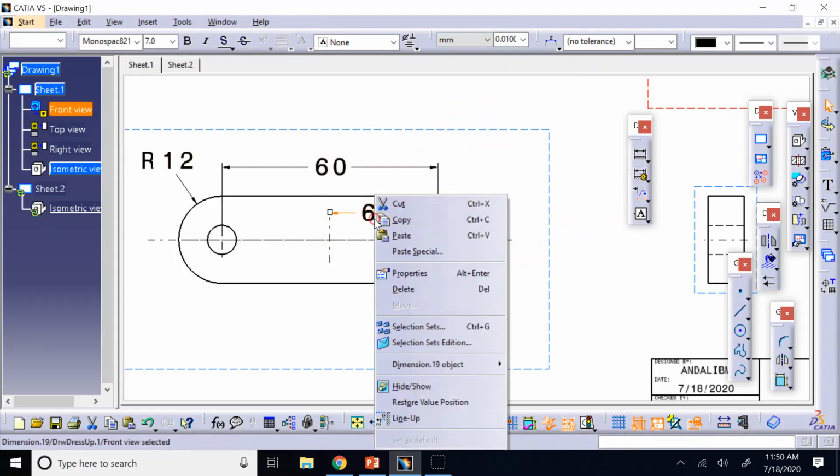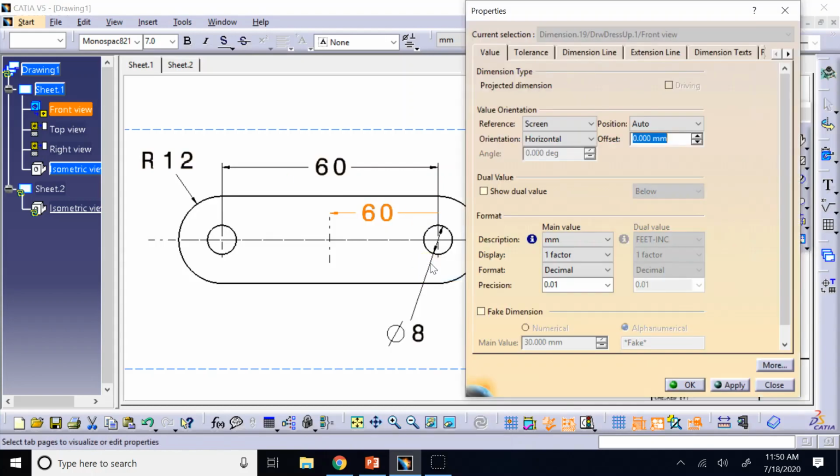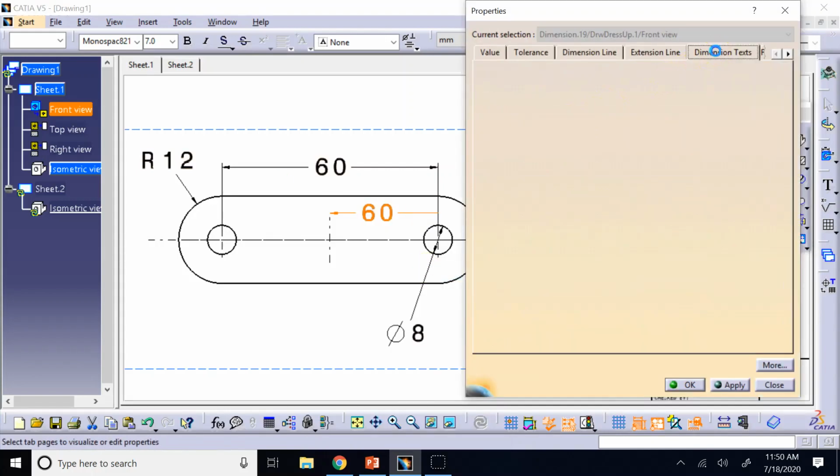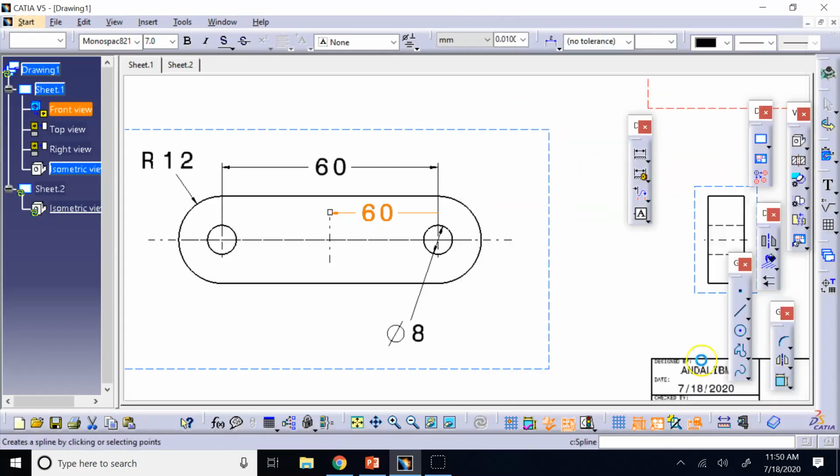First of all, you see, it gives me the wrong dimension and says this is 60, which is not, it is 30. So it is confused a little bit, actually. And you should not do that. Why? Because I have this symmetry. And when I have the symmetry, it means this distance is the same as this one. So this left distance and right center to center of the part, they are the same. And the whole thing is 60, so each one is 30. So even if you provide 30, that's redundant. Don't do that.